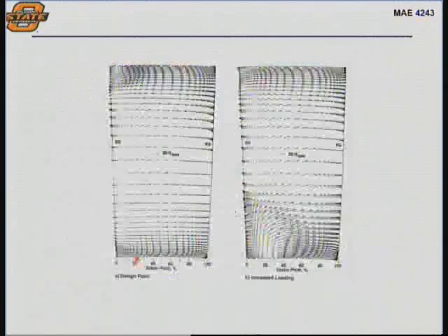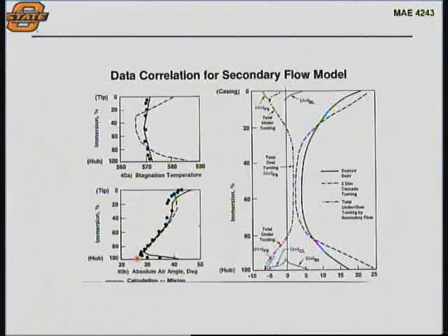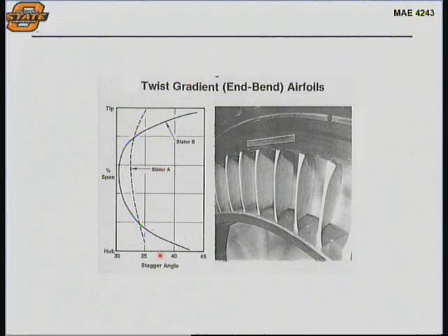As you might imagine, if you design blades with this type of secondary flows, especially near the casing, near the tip, and near the hub, it's going to want you to put air angles in kind of a weird way relative to a uniform twist, if you would.